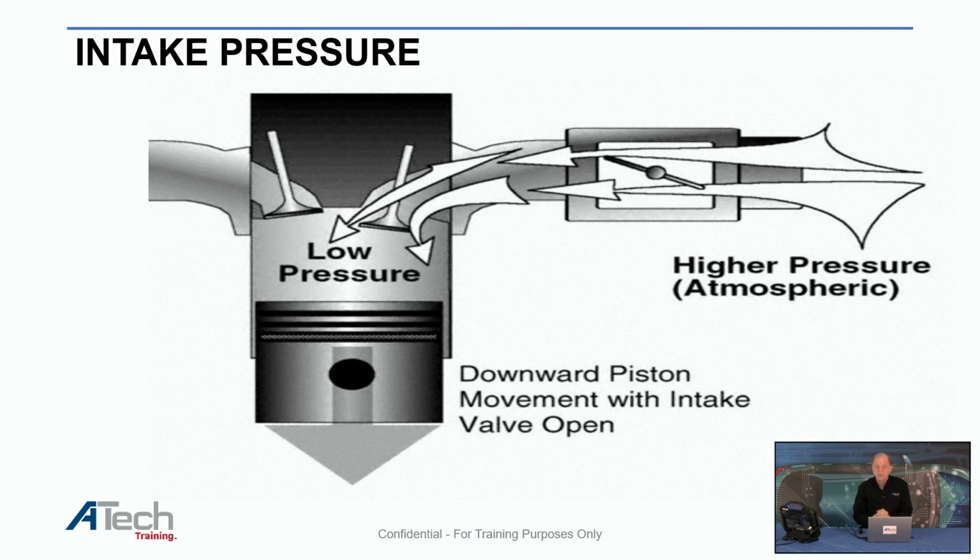Now, again, what I wanted to show you here is we have high atmospheric pressure, 14.7, or 14 depending on your altitude. You always lose about 1 inch per 1,000 feet, okay? So you have the restriction. Anytime you have a restriction, you will keep the flow down, you restrict the flow, you will create a vacuum on the other side of the restriction.